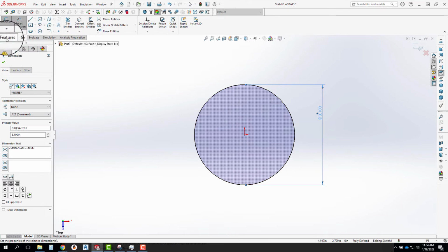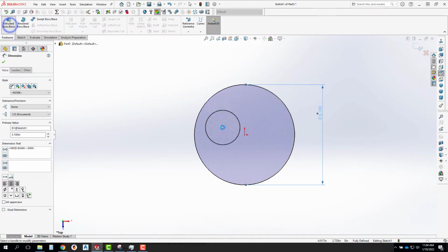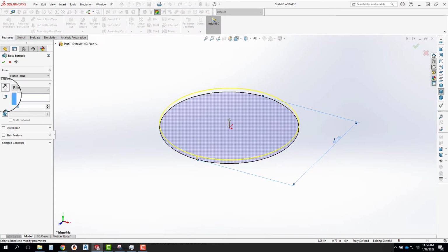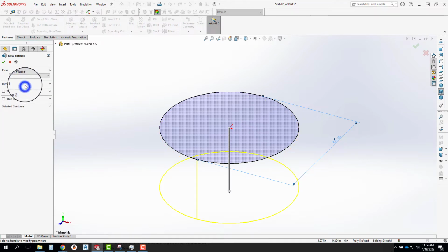And then I'm just going to extrude that out. And I'm going to extrude down. And looks like the cup has a depth to the very bottom. It would be 1.55 because the inner depth of the cup is 1.5 inches, and then again the wall thickness on the bottom would be 50 thousandths. So I'm going to extrude out 1.55, and now here I'm going to take advantage of the draft tool to put that 10-degree taper on it.